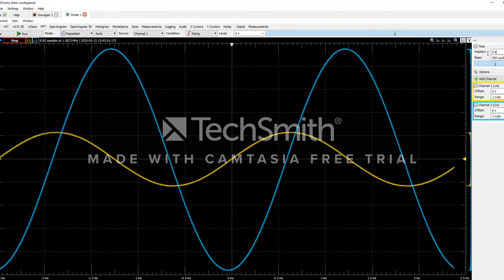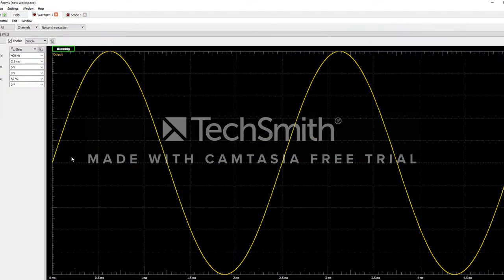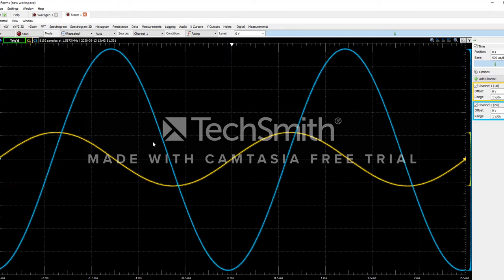Okay, nice. So one thing to note here is the input waveform starts at 0, right? One thing you should immediately observe is the resistor voltage, which is on channel 1, the yellow channel, is in phase with the input voltage.